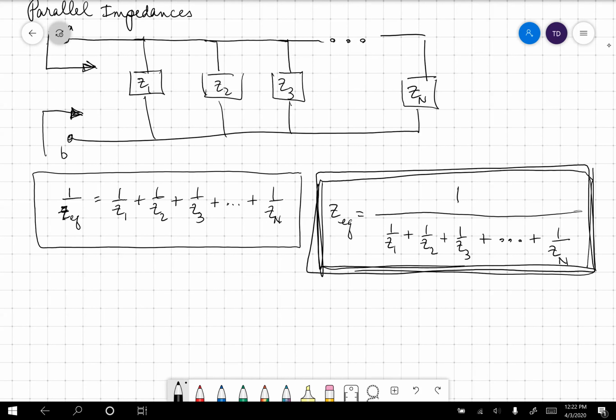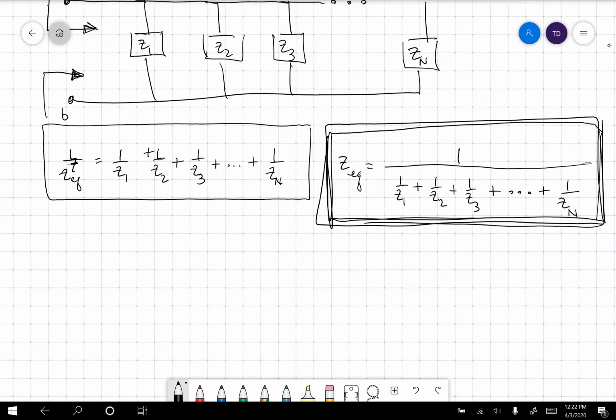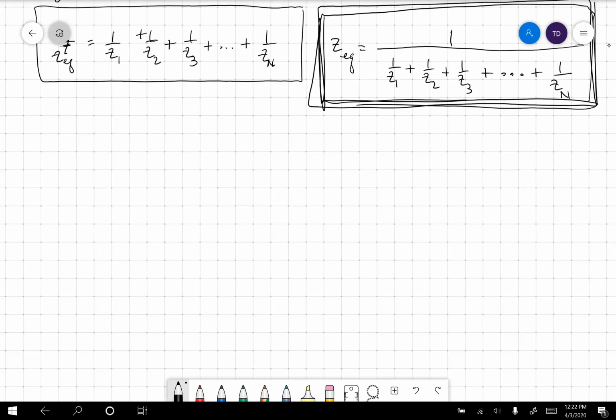Because what did we say to do when you have multiple things in parallel? Just do product over sums and then keep moving along. Reduce it to two, product over the sums, then group that result with another one, and just continue grouping with twos.